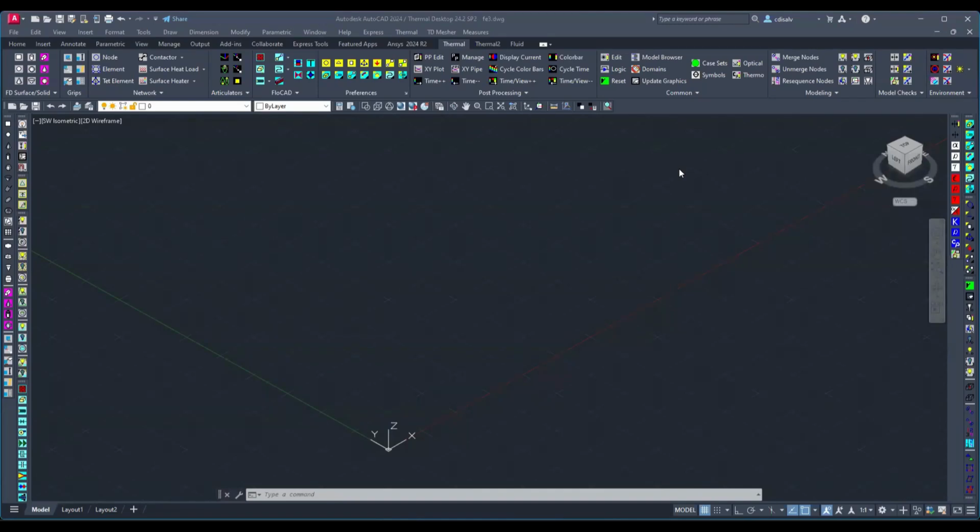Hello, this is Chris DeSalvatore, and in this tutorial, we're going to be creating a finite element model, and then we'll generate a single quad element from that. Then we'll use the AutoCAD array command to create a grid of elements, which we will then extrude and revolve into 3D solid elements. Then we'll input radiation to the elements, applying temperature boundary conditions and solving the problem running SINDA. So let's get started.